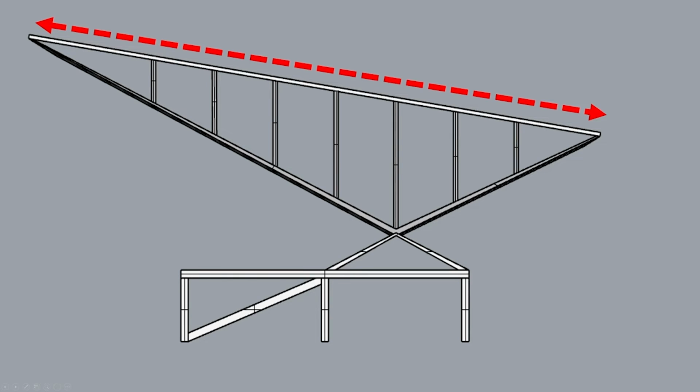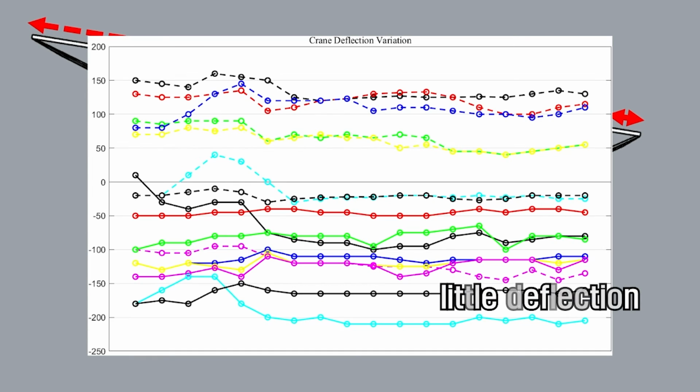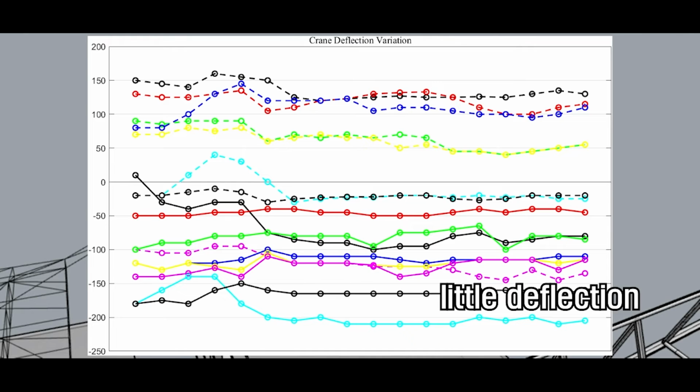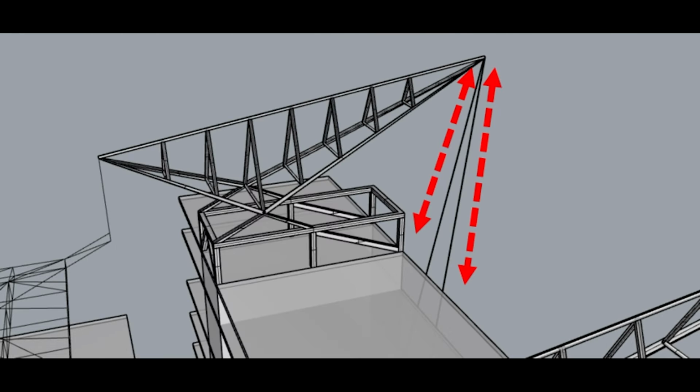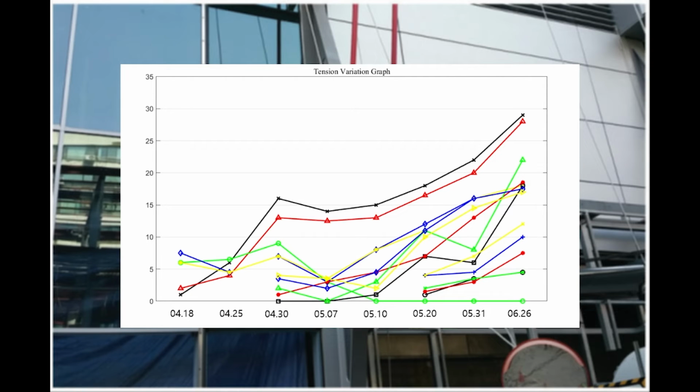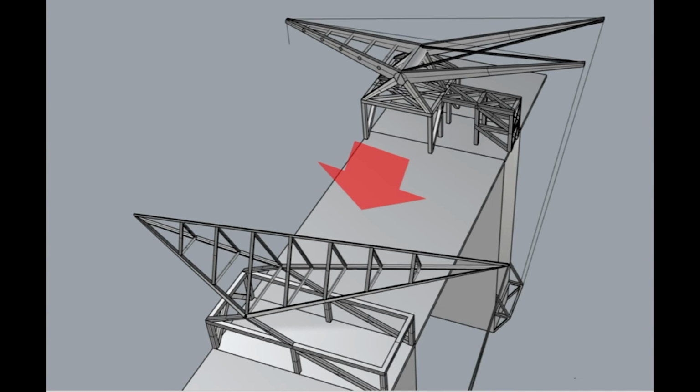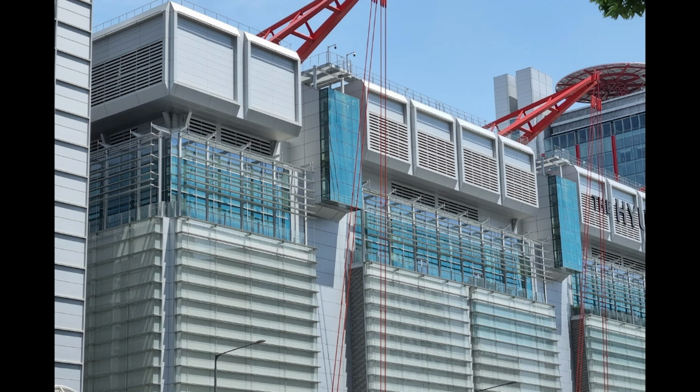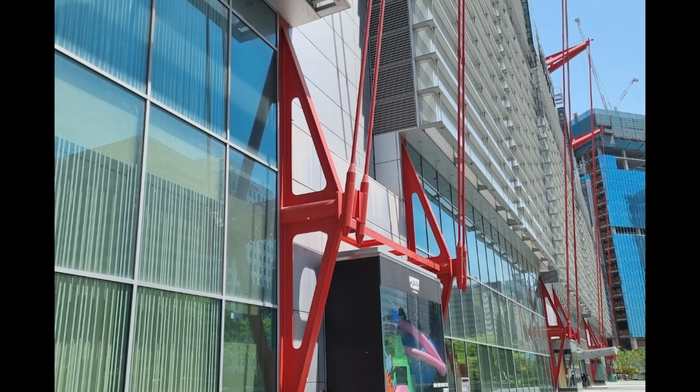On the other hand, in the case of the cranes, there was little change in deflection due to additional loads from the stable point, but the actual tension applied to the backstay rod was found to be larger than the analyzed tension, so reinforcement was considered. Fortunately, thanks to the change in the design of the crane to enhance stability, the work was completed without additional reinforcement work since the actual tension was in the range of the design strengths.